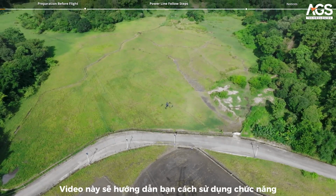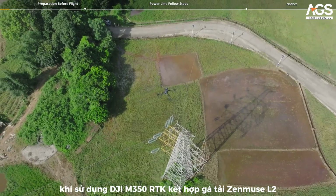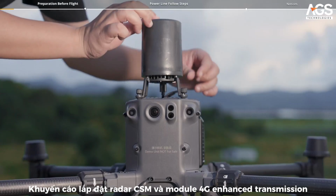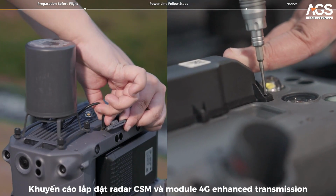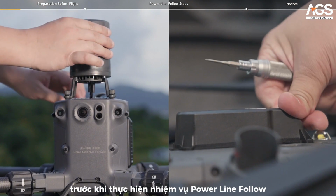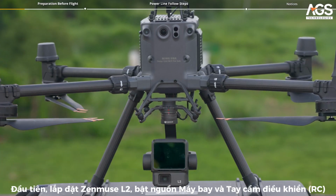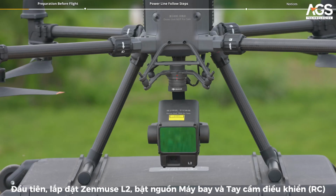This video will show you how to use the power line follow function when Matrice 350 RTK is mounted with Zenmuse L2. It is recommended to mount the CSM radar and 4G enhanced transmission module before performing the power line follow task. Install Zenmuse L2, power on the aircraft and remote controller.